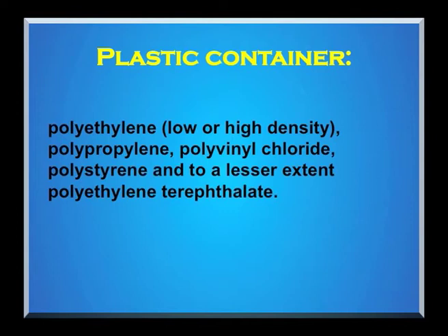Additives present in plastics are plasticizers, fillers, anti-static agents, antioxidants and other ingredients added for special purposes. Plastic containers for pharmaceutical products are made from plastics based on the following polymers: polyethylene, that may be low or high density, polypropylene, polyvinyl chloride, polystyrene and to a lesser extent polyethylene terephthalate.